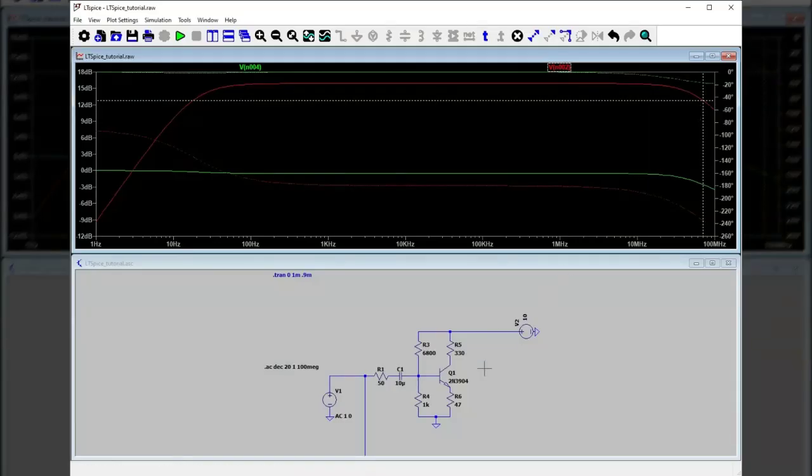All right. Now, there's nothing here in the schematic that would be indicative of what the higher 3 dB frequency is. This would all be infinite bandwidth as far as what's showing here on the schematic. But of course, the device model has capacitors in it, which make the frequency response roll off at high frequencies. So that's what's going on there.